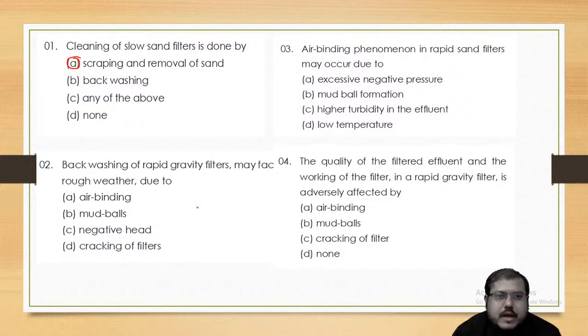Question number 2, backwashing of rapid gravity filter may face rough weather due to its mud balls. We've discussed operational problem. Question number 3, air binding phenomena in rapid sand filters may occur due to excessive negative pressure. Then only air will be entrapped between the pores of the porous media or the sand particles.